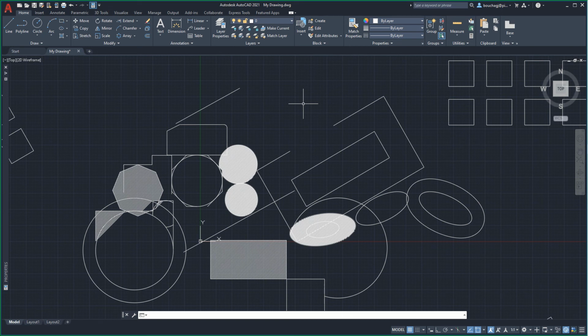In the next video, we will explore annotation objects and elements such as text, dimensions, and leaders, creating layers to manage your drawing content and drawing output, and at the end of this next video, we will save our own personal drawing file into the AutoCAD templates folder, and we will repath the new drawing saved path so that our personal drawing template file is opened each time AutoCAD opens or we select to open a new drawing file.